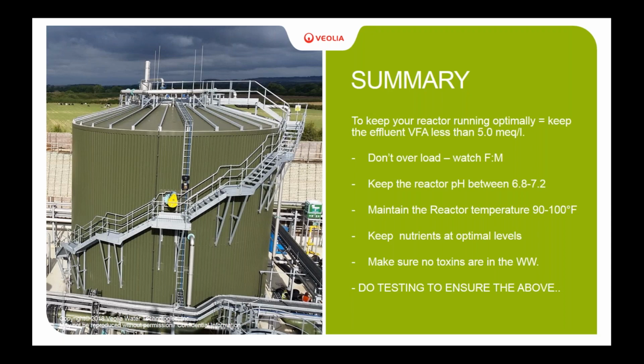And obviously, in the end, if your system has been running very well for weeks and months and years, and all of a sudden, out of nowhere, your COD removal rates go down extremely badly and your biogas goes down to nothing, most times that points to a toxic event that occurred. Something came down from the waste treatment plant that inhibited, hopefully it didn't kill, but inhibited your biology.